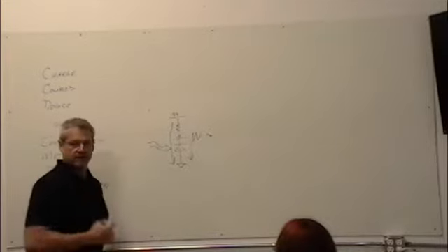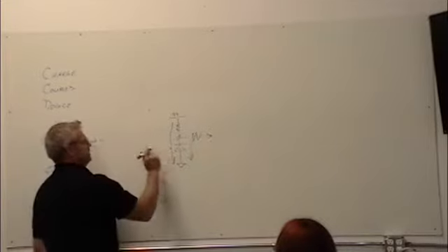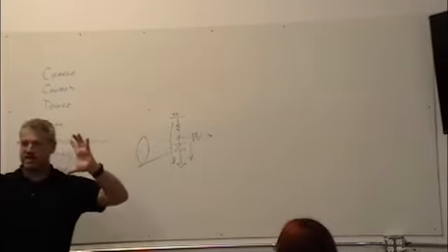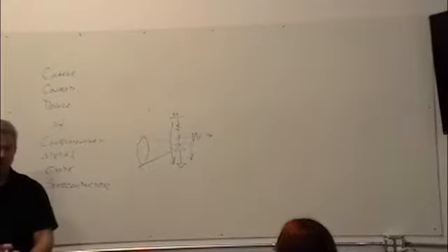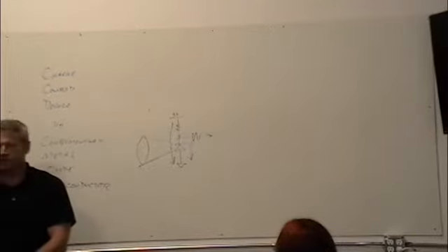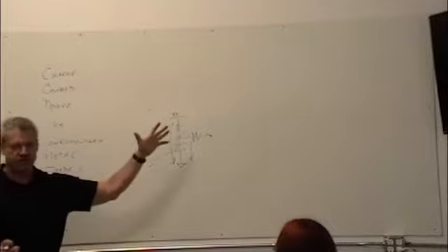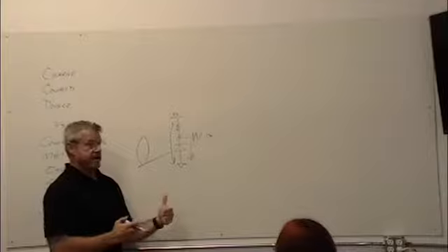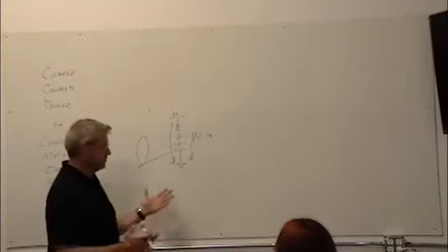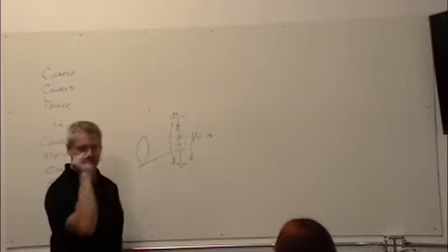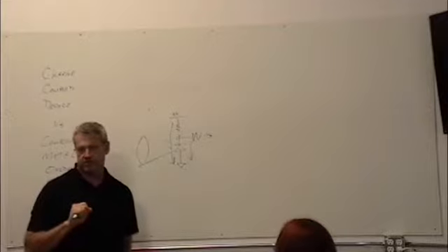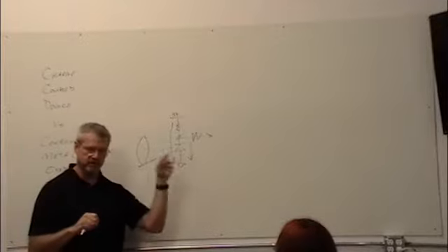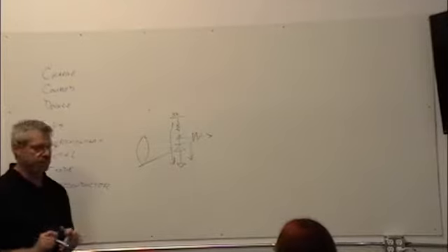And so if I make this, say, a 5 or 10 k ohm resistor, I'm going to see a voltage change here. Hey, once I figured that out, now I can put a lens in front of this and focus light on it. Now I've got a big area, focusing a lot of light into a small area, and I can get a big change in current for a relatively small change in ambient light. So, hey, that's useful. I can do all sorts of fun things with that. I can shine a light off of something, and if I've got a fast enough counter or an oscilloscope, I can see how wide that pulse is, and I'm basically doing the radar equation with a light beam now. I can see how far away things are.